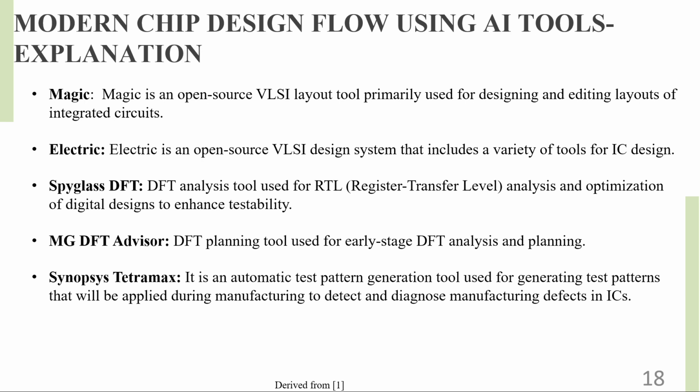MG DFT Advisor. It is a DFT planning tool used for early stage DFT analysis and planning. Synopsys TetraMAX. It is an automatic test pattern generation tool used for generating test patterns that will be applied during manufacturing to detect and diagnose manufacturing defects in ICs.